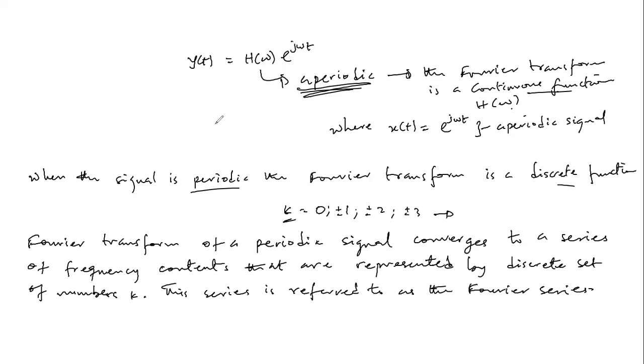But when we take the Fourier transform of a periodic signal, because of the fundamental time period, we see that the frequency contents are represented as a set of discrete numbers. And all we can then talk about is the linear combination of these frequency contents, which are of discrete sets from probably 1, 2, 3, 4, 5 in terms of their harmonics.